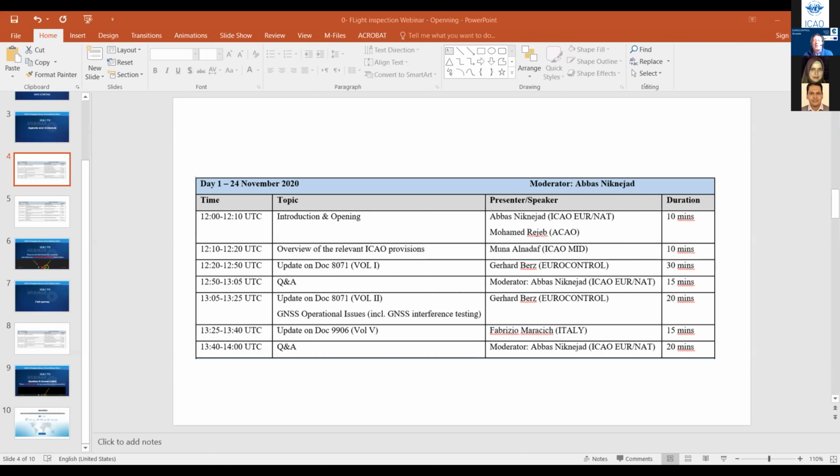Regulation in Doc 8071: if the flight check of the nav aid shows everything seems normal, how could we rely on the aircraft receivers themselves? Actually, one of the funny problems that people had is that in some cases more modern flight inspection aircraft got more accurate and sometimes put the facility out of tolerance because they got more accurate. But again, on aircraft receivers, there are calibration processes that need to be done. You need to correctly have under control the antenna, the cables, and the receivers, and they need to be part of your calibration effort, and that is described in Doc 8071.